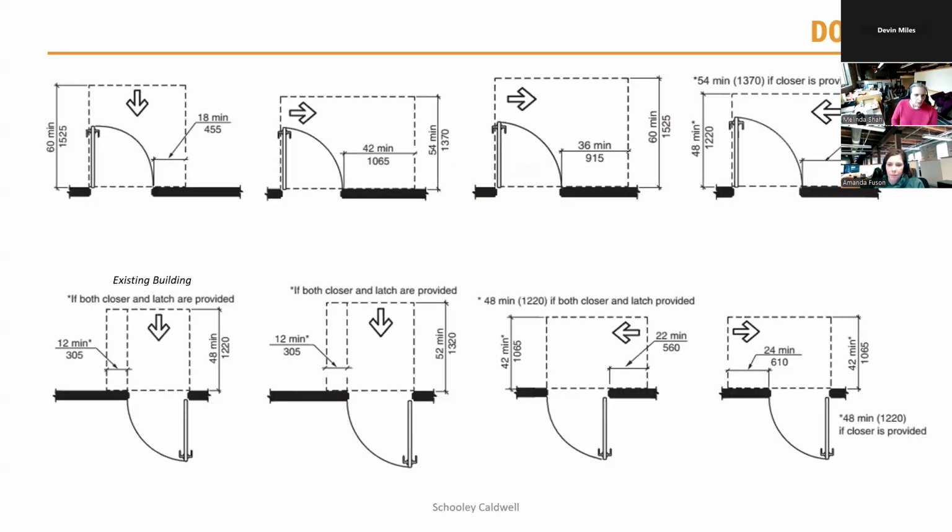When it comes down to doors, they have lots of different clearances required. Depending on how you're approaching the door, from the latch side, the hinge side, the pull side, the push side, every different direction has different clearances. They are also impacted if your door has a closer on it, one of those things that automatically keeps your door closed, like a fire egress door should. You need a little more wiggle room, because if you have to hold the door open because otherwise it closes on you, that is a different task than a door where you manage to get it open, go through, and then close it. Generally, well, there is no general when it comes to doors. They all require a lot of different clearances. So when in doubt, look it up.